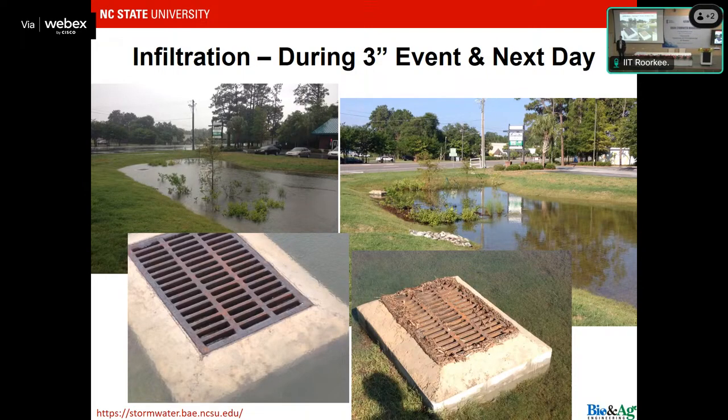This particular site, we infiltrated a lot of water. The water table was between 1.5 and 2 meters away from the surface. And you can see we had a 75 millimeter storm. It filled it up. And then the next day, most of that water had soaked back into the soil, which was great. So infiltration is a great way of removing volume, which helps stream health, to let that water soak into the ground.